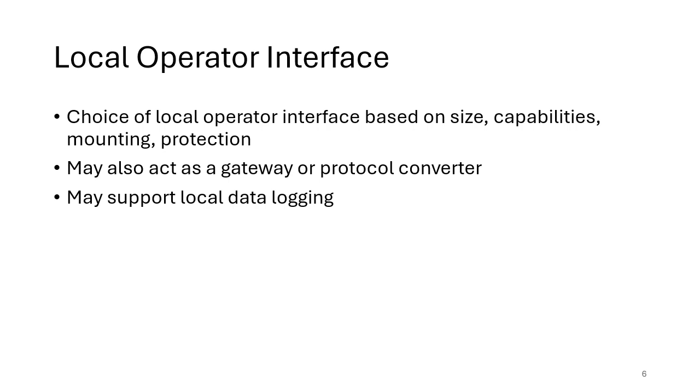How is it going to mount? Typically it mounts in the panel itself, but you might have something that needs standalone mounting, and the mounting might define the protection. So you might have an IP66 panel at the front, but it's IP20 at the back because it goes inside the panel. But if it was freestanding, maybe you need a higher level of protection, but that's going to depend on what your application is. So for example, something that is hosed down maybe needs to be stainless steel and IP67, but something that's in quite a benign atmosphere, IP40 or 54 or something along those lines might be suitable.